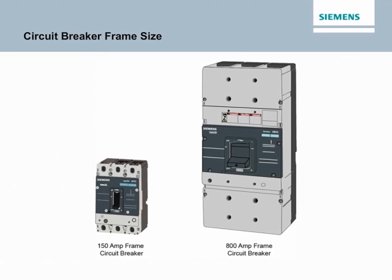The circuit breaker frame includes all the various components that make up a circuit breaker except for the trip unit. For any given frame, circuit breakers with a range of current ratings can be manufactured by installing a different trip unit for each rating. The breaker frame size is the highest continuous current rating for a breaker with a given frame.